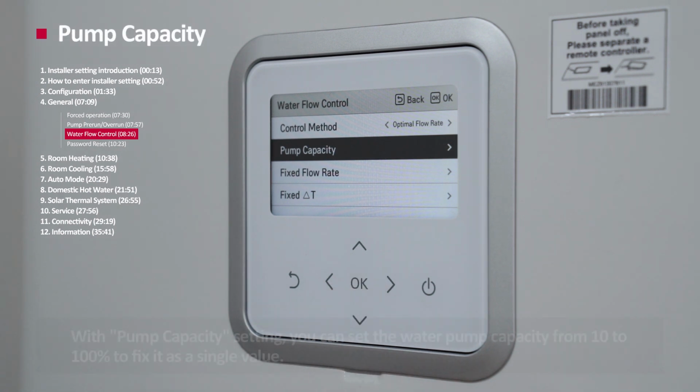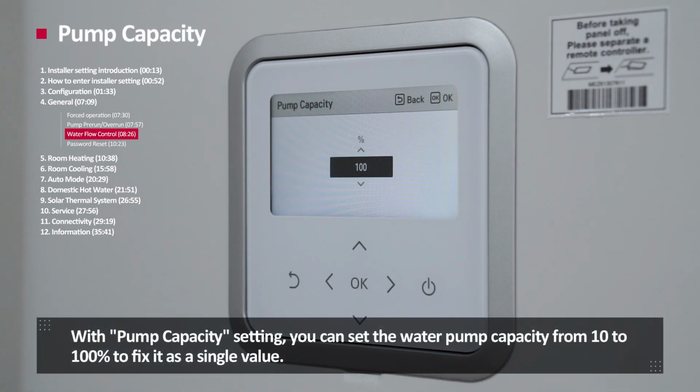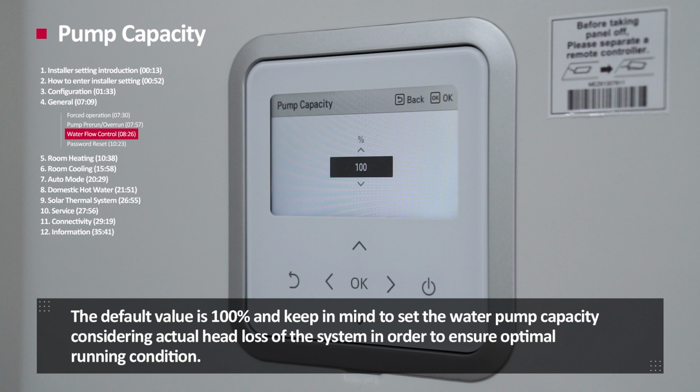Pump capacity. With the pump capacity setting, you can set the water pump capacity from 10 to 100% to fix it as a single value. The default value is 100%. And keep in mind to set the water pump capacity considering the actual head loss of the system in order to ensure optimal running condition.